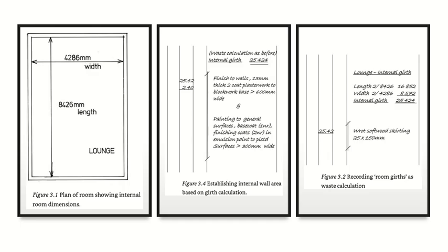This skirting needs length, and to calculate the length, I need to calculate the perimeter. And how do I calculate the perimeter? Like this. Showing how you got the perimeter is waste calculation, and the perimeter itself will go here in the dimension column.